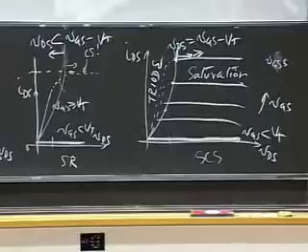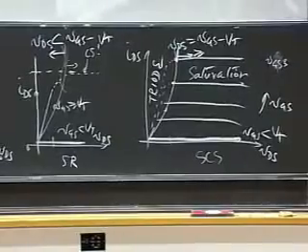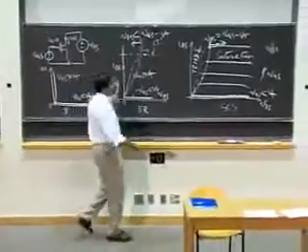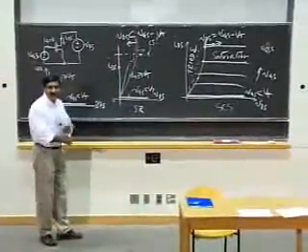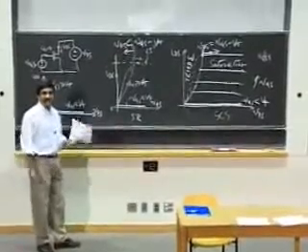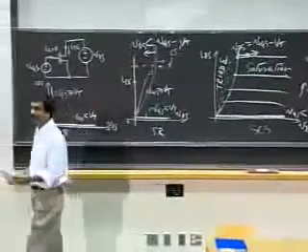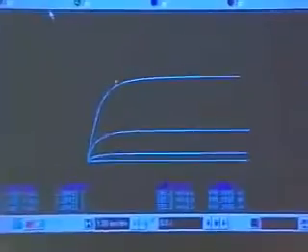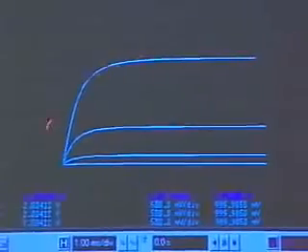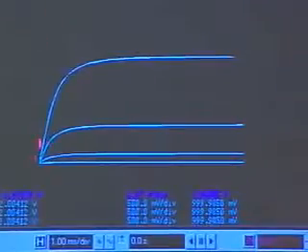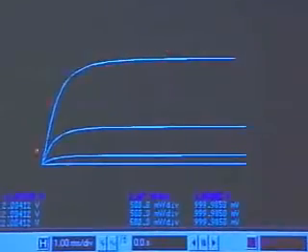So what I'll do is show all the curves. We've plotted for you, for the MOSFET, all its characteristics in its full glory for a whole bunch of values of VGS and a whole bunch of values of VDS. And let me stare at those curves with you for a few seconds and walk you through them. So what do I have here? One of these curves corresponds to a given value of VGS. Okay, this may be VGS equals 2 volts. This is VDS, the drain to source voltage, and this is the current. So focus on this curve for now.